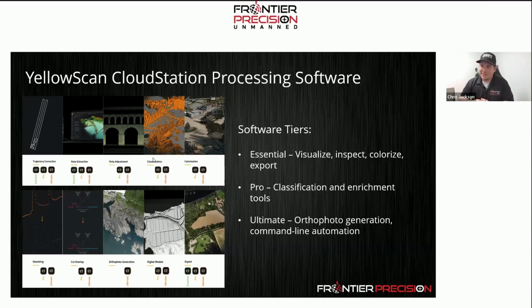When we're flying, we usually have about a 30 to 50% overlap between our flight lines. This tool basically removes any of those duplicate points, leaving any unique ones, and helps you manage those data sizes and removes the stuff that you don't need.